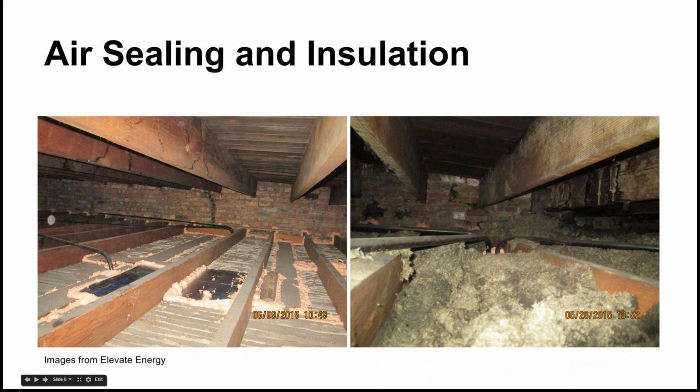But there's a problem with this, and that's that too much air sealing will prevent the house from being ventilated properly. If you just seal up every square inch that is open, then things like combustion products, smoke, and moisture will all stay in the house. So if you're going to be air sealing your home so it's super tight, you have to address this by adding mechanical ventilation, so getting fans that blow indoor air out and replace it with fresh outdoor air.